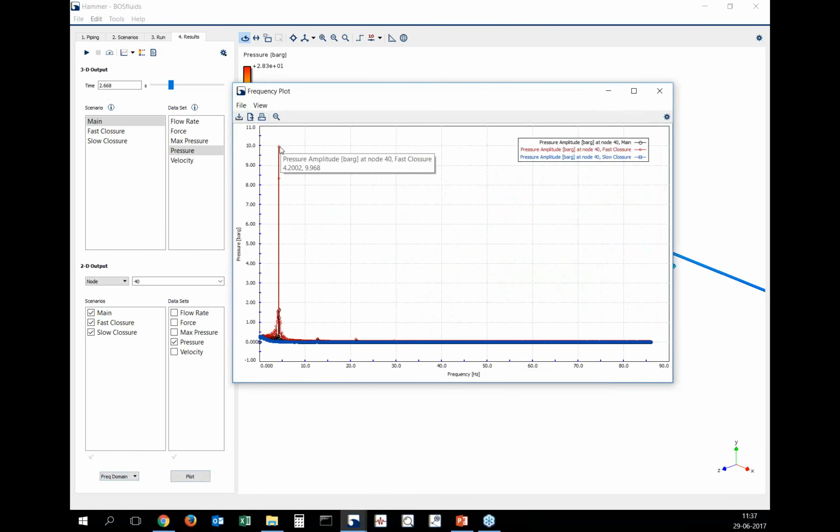So you might want to take that into account and compare that with the mechanical modes of the model, and see that none of the mechanical modes can cause a resonance with this 4.2 Hertz acoustic frequency.